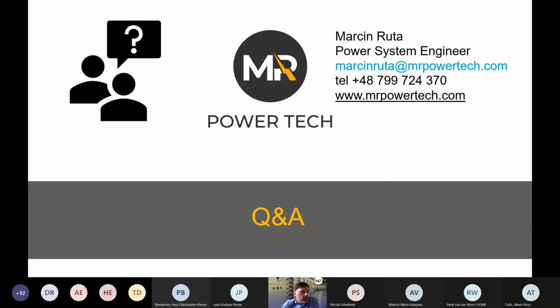Can you suggest the minimum voltage and ampere to consider arc flash hazard? As I said before, you might start, as a rule of thumb, depending on where you are, from the 208 or 230 volts level, and then 63 amp miniature circuit breaker protection, which are B, C, D types. If you start from this, there's usually not much to add, but if you have to, there will be maybe a few locations. Even if you do it, it's very likely that below 63 amp there will be no arc flash risk, or the arc flash energy will be below 1.2 calories. Not always, but in most cases.